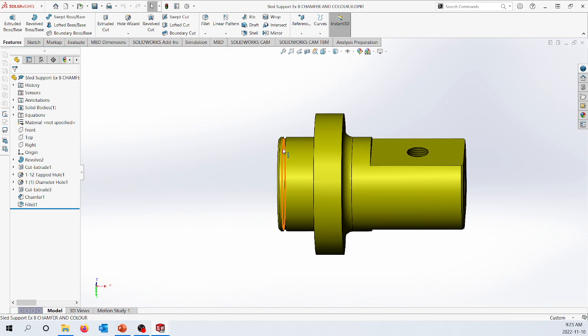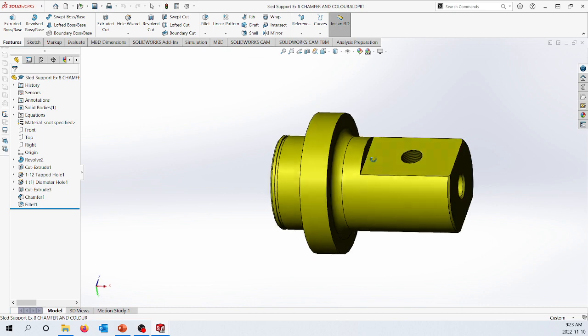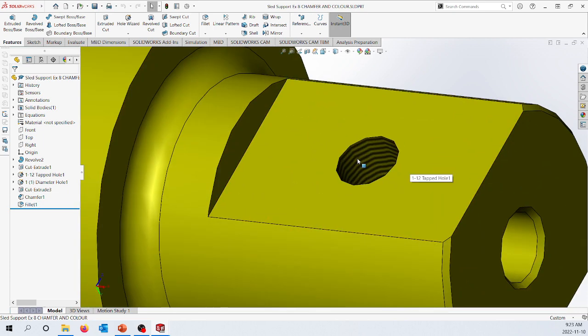That will clip around into this groove almost all the way around and prevent anything that's stuck between here and that clip from sliding on and off. And they're nice because they distribute the load all the way around that groove, rather than, if we had a bolt, it would just be at the two ends of the bolt that it would be able to put that load on. Then we have over here a threaded hole.